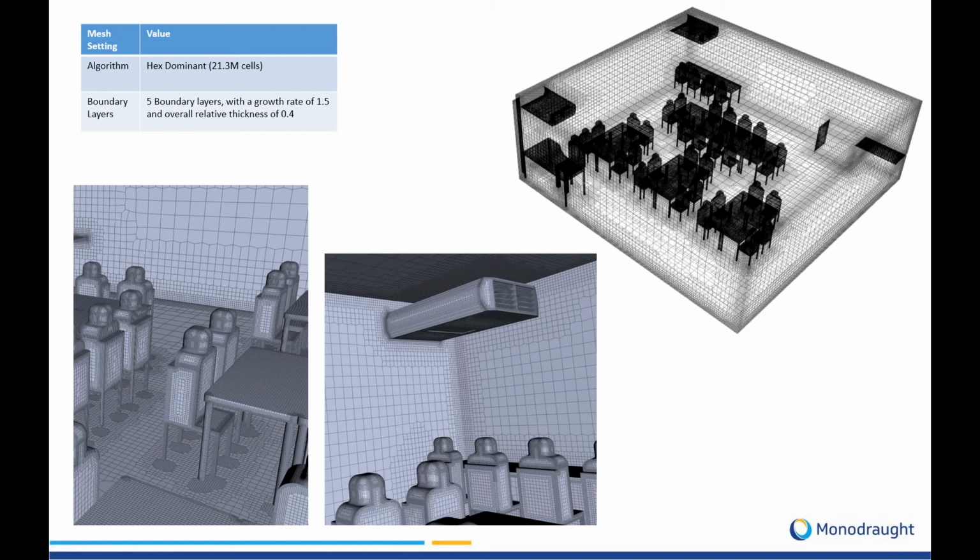But within the design, we come from a base of natural ventilation with openable windows, and as such, we've tried to keep the design within that remit of minimum amount of energy use through reduction of the resistance, but also the reduced maintenance aspect. And we know many instances of trying to get our ventilation systems maintained. We sell maintenance contracts in things like schools and colleges, and it's a hard process to get stuff maintained correctly. And by having filters in there, if they're not changed, then the performance is degraded very quickly.